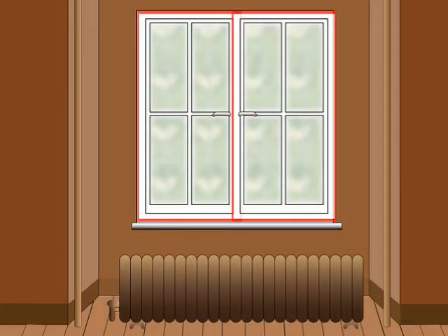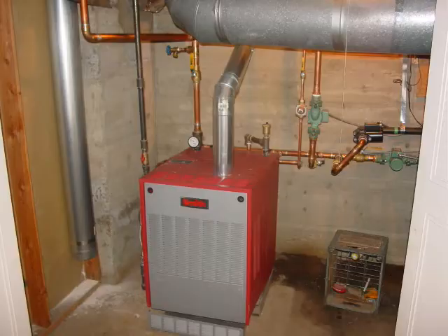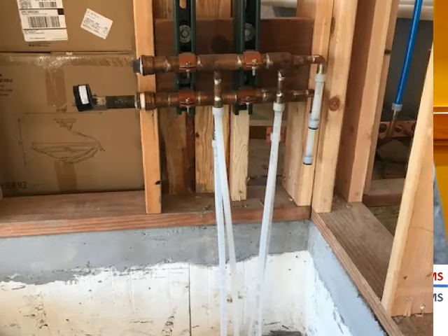Let's look at a system that doesn't use ducts to heat an area, like radiant heating. We have two typical methods for this. Electric radiant panels can be used. The second is hydronic, so hot water, that is directly circulated through the panels at various locations, floors or walls. Electric radiant systems have electric cables built into panels. You can build it into the floor, you can build it into the wall. Hydronic radiant systems pump heated water from a boiler through tubing in the floors or walls.